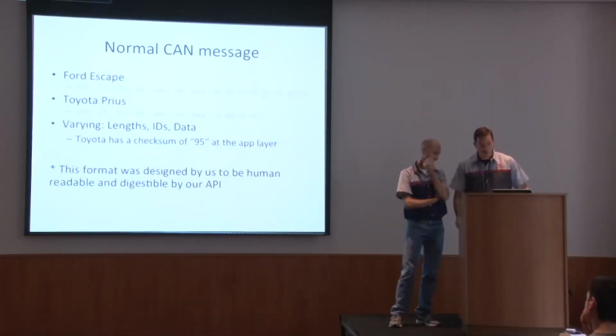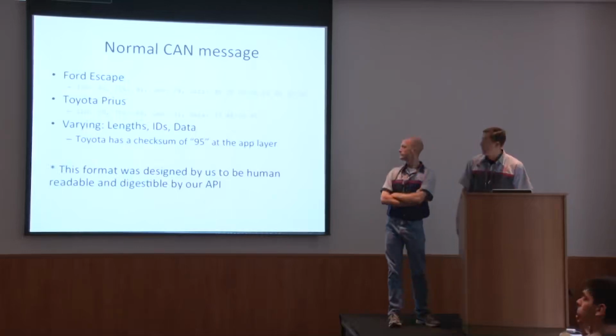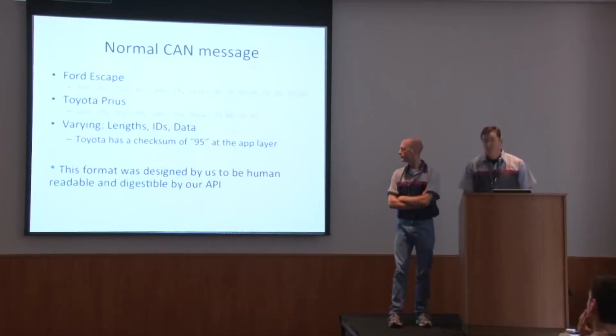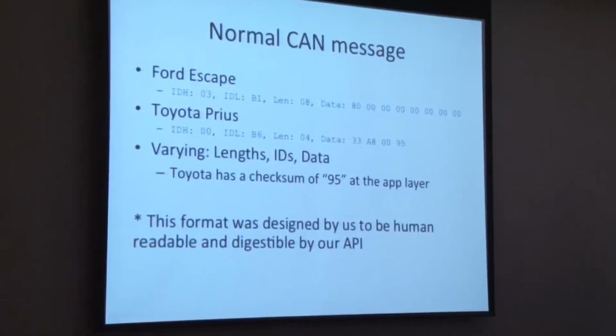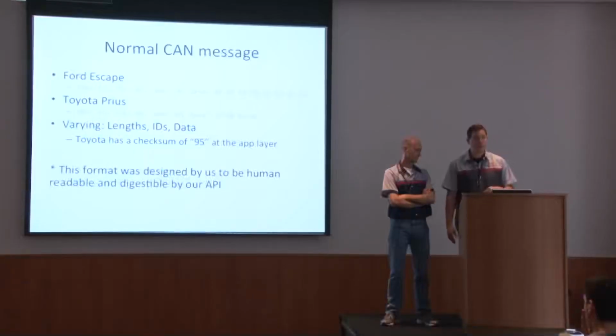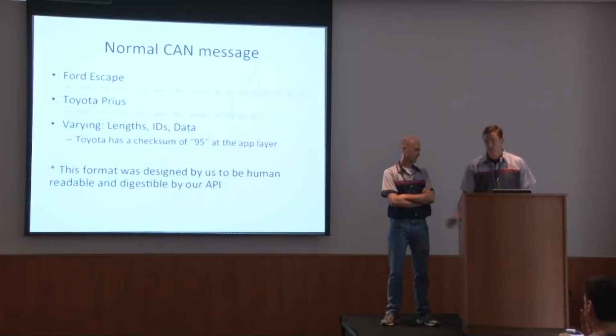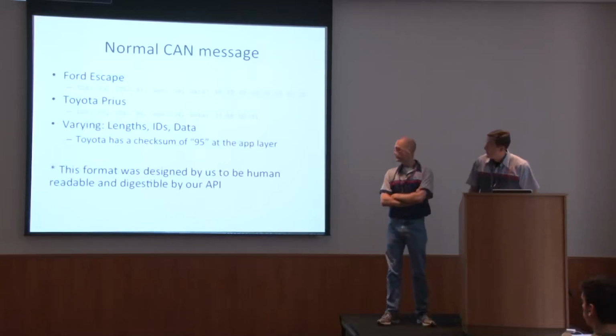These are example messages, the first being from the Ford Escape. This data format was invented by Charlie and I just to be human readable and digestible by our API. This isn't some standard definition. As you can see here, there's one message that has a combined ID of 03B1 and a length of 8, followed by 8 bytes of data.